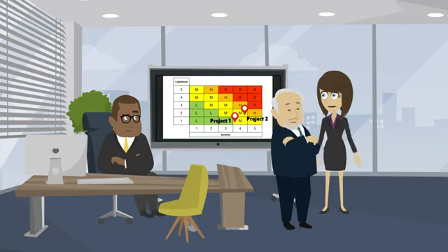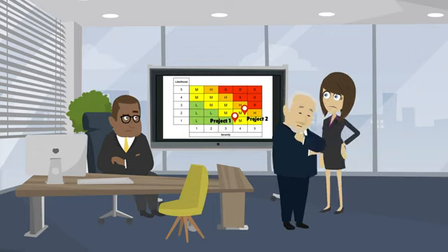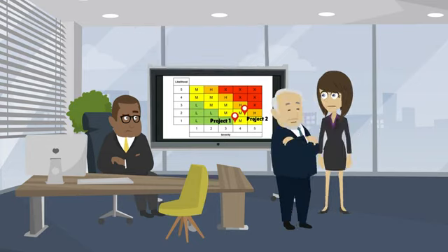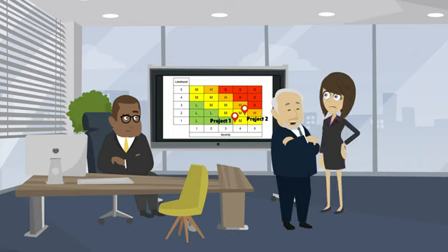Is the sensor and the valve to shut down independent from the cause of overpressure? Oh. But in the HAZOP, there aren't any rules stating that the safeguards must be independent, nor is the risk matrix clear about the action required for medium risk. I don't think we overspent with the high-integrity overpressure system. Our engineers were not comfortable using the existing control as a safeguard. Well, our team decided it was good enough without additional safeguards. We have an existing facility that operates the same way.